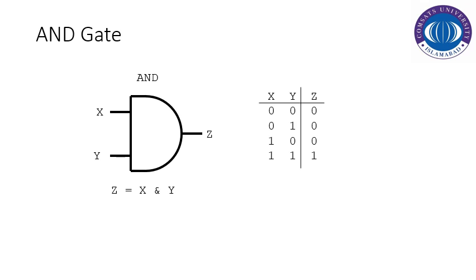Now coming to the AND gate. The AND gate performs the AND operation. You can assume that the term AND which we use in language is the same term used to link two phrases or two terms. For the AND operation, if both the literals are true, or both are 1, then the output is 1. Basically, the AND gate provides logical multiplication. It's not decimal or basic multiplication.